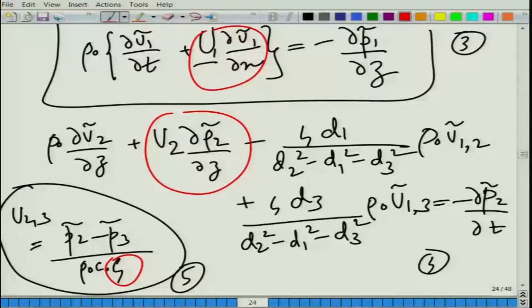We still assume our small segments do not vary much, and we can probably analyze a special muffler configuration called a CCTR, conical concentric tube resonator, where the outside cavity is of conical shape. Then we can use this matrix approach in its full form. It completely harnesses the power of this nice mathematical approach. So, this is something here.